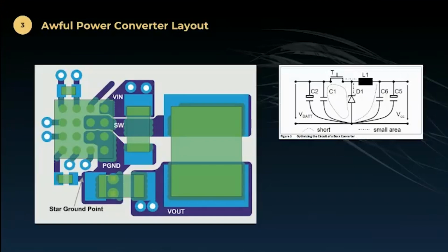In this particular case, it's especially egregious because if we look at, let's see, there's a V out. So this is the switching node. That's pretty small, but then they routed their input capacitor right over the top of the switching node. And the input capacitor is connected to VN, and that takes it right out to the LISN. So routing the input capacitor over the top of the switching node, definitely a bad idea. Their switching current loop goes through, there's VN through that to ground and takes it back.